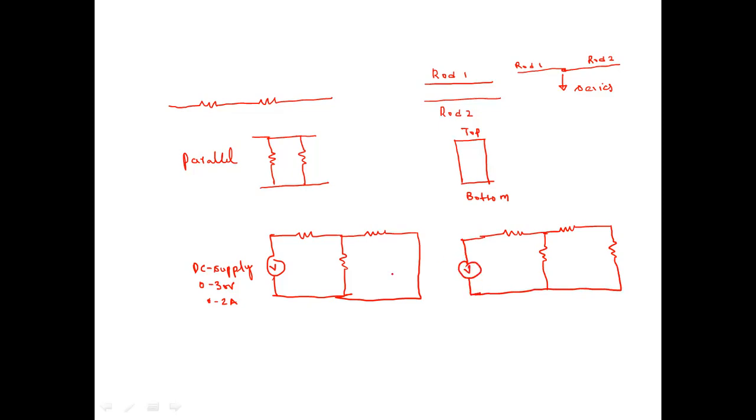what you need to take into account is that you need to label the circuit. I'll label the circuit, starting from the start point, A, until there is no element connected in between. What is an element? An element can be a resistor, a voltmeter, or an ammeter. Ammeter is basically connected in series. So the potential of the point will not change. This potential A will remain up to it, but across this there is a different potential. This potential over here would be B, and same up till here.